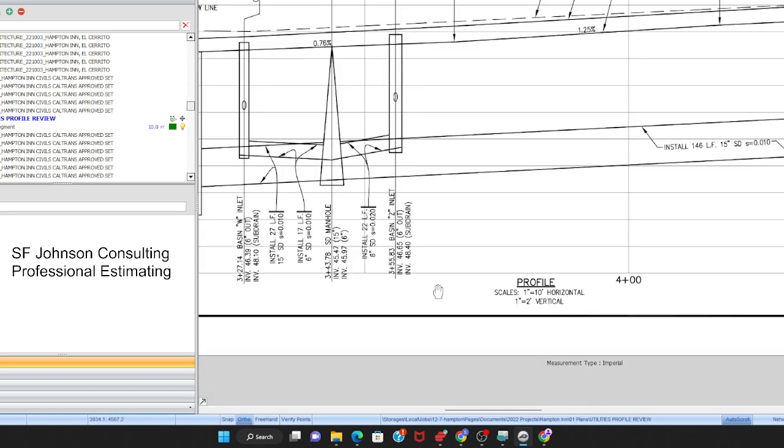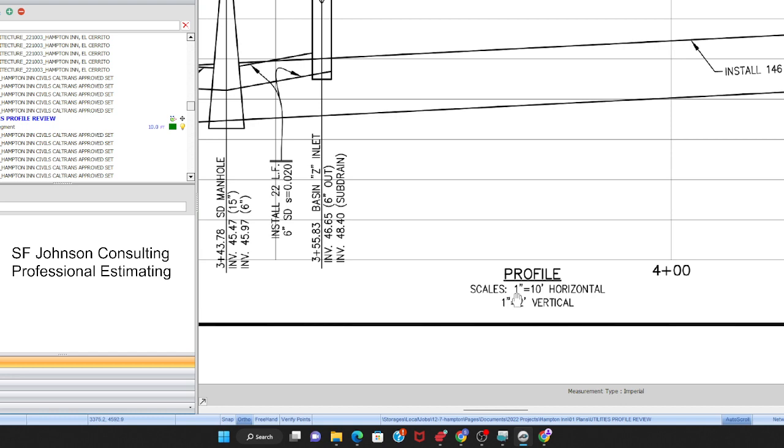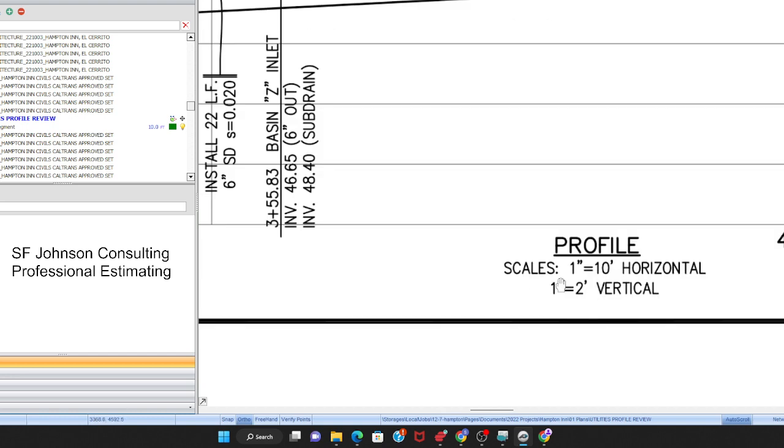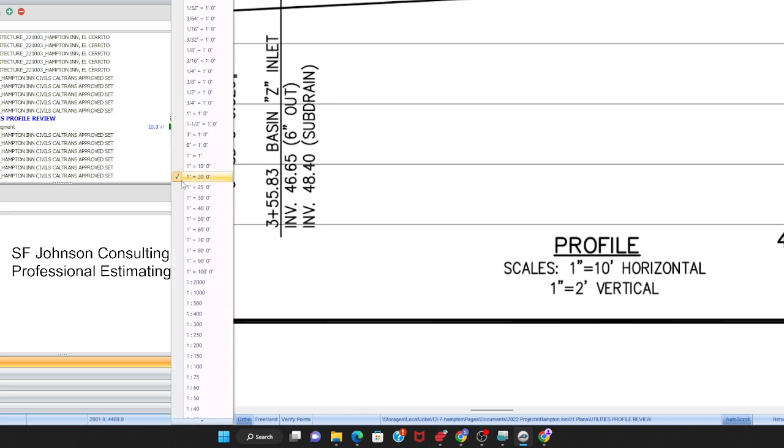So I put it on scale, and I did 1 equals 20, because they're on any normal scale. You're not going to get this for every 1 inch. You have 1 to 1 foot, but so you can multiply that by 2. There's a number of ways you can do it as long as your multiplier is good. Well, what I did is, which one did I use? I use 1 inch equals 20 and divide by 10. So basically each one of the vertical divisions is 1 foot.